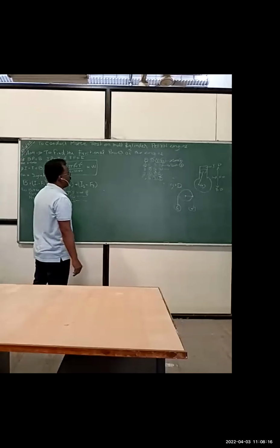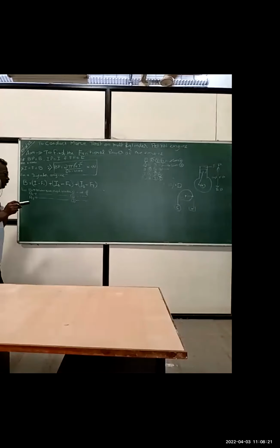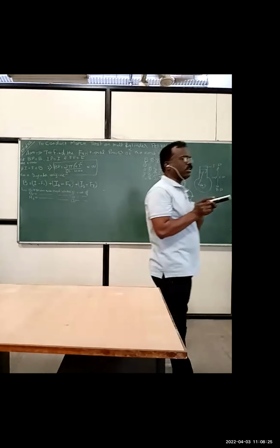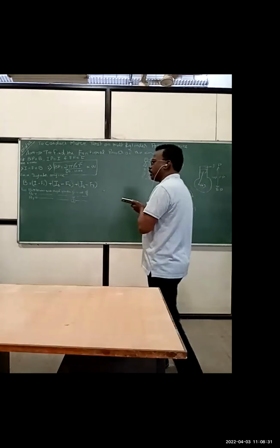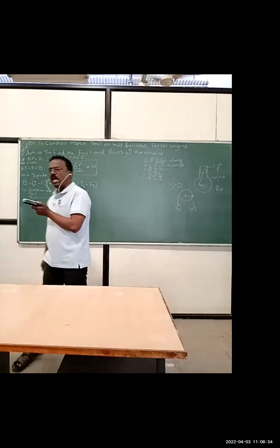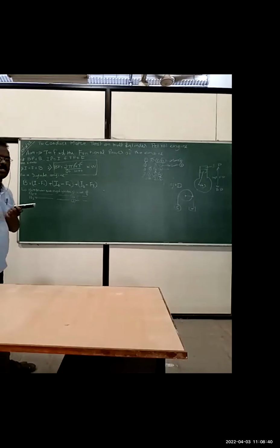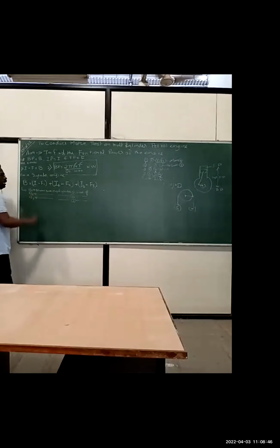We have a contact type of tachometer, where the tip of the tachometer has to be pressed against the center of the rotating shaft, the output shaft or crankshaft, where the tip also starts rotating at the same speed as the shaft, and therefore we can see on the display of the tachometer the rotational speed of the engine. Okay, so this we know, and once we measure this, now let us move on to our engine.